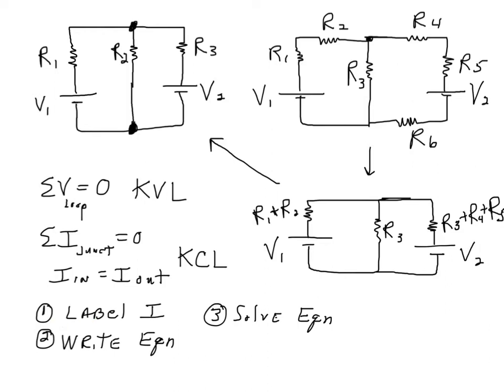One, we're going to solve it by means of Kirchhoff's laws. So the first step is to label the currents in the circuit. So that's what I'll do. And there are three currents, one here, and one here. Two junctions, three currents.